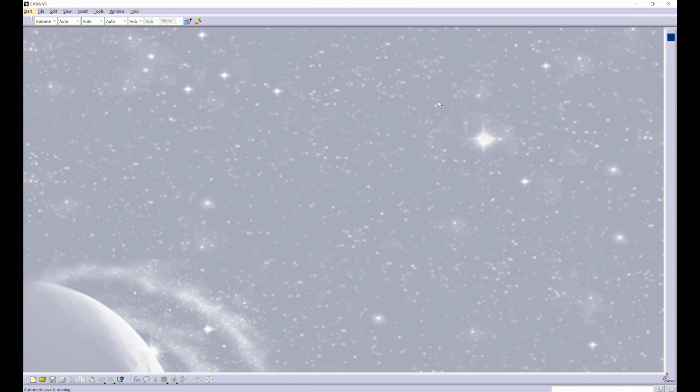Okay, let's go into the CATIA environment. First Control plus N. Then this tab will pop out. Let's go to Part, then click OK. A new part tab will pop out, so we can rename this as Sample 1.